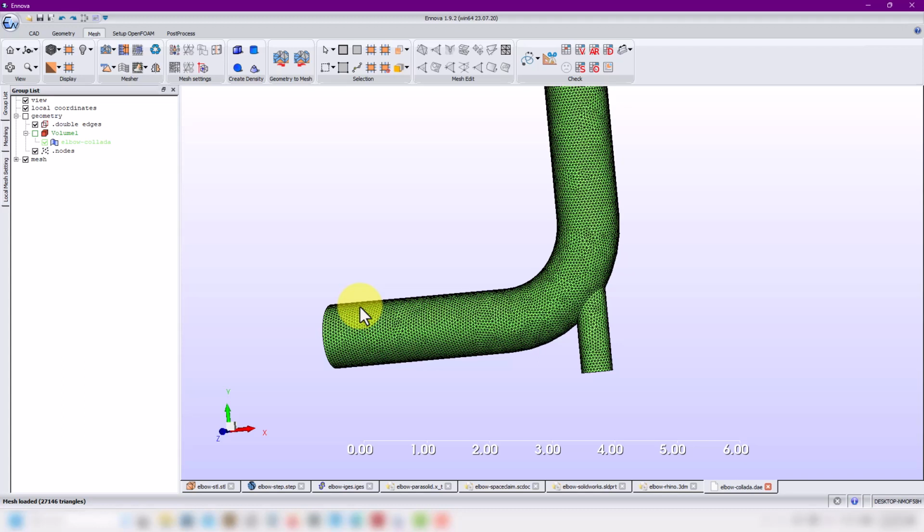So pick up a good format. Don't say STL or this format. You need to pick up the right format to have all that information. Personally speaking, I recommend the STEP format. It's a very good one. Also Parasolid, and then you have all the commercial ones. ProE, Solid Edge, AutoCAD, CATIA, all of those formats work fine. And IGES is not a good one. STL also is not a very good one.